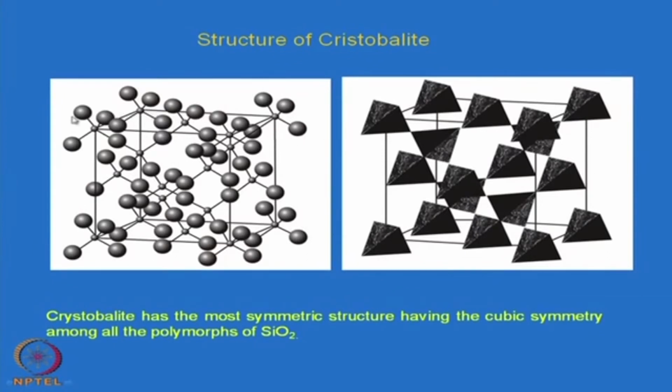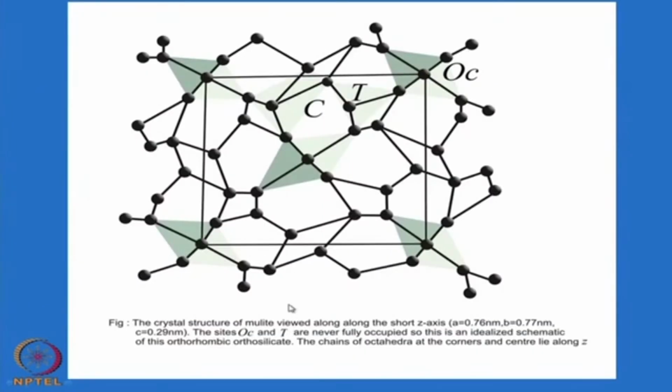These are the details of the atoms, once again within the framework of a cubic structure. At each corner you have 4 different ions, one silicon ion, and surrounding it 4 oxygen ions. That becomes a repeating unit in this structure. So, that is the description of the crystalline form of silica.